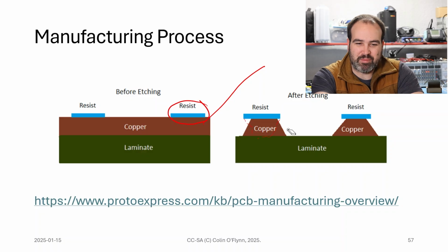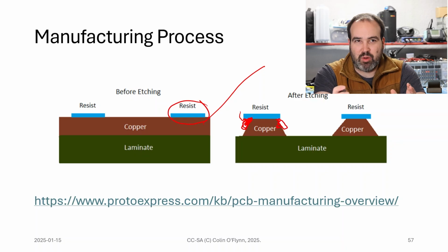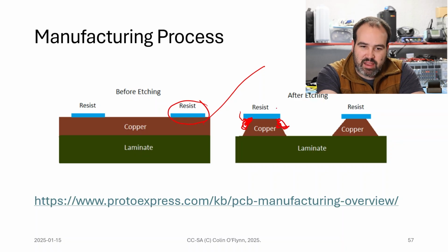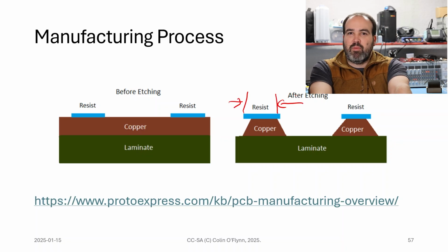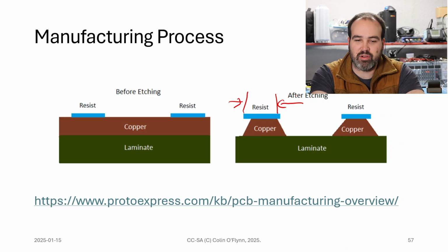You end up with this problem that basically you have this under etch, right? So under the resist, etching happens here, so the trace widths get too narrow. And so whatever our design traces are, they can be a tiny bit narrower than we meant them to be. So obviously, if this width, this goes back to our trace space, is really small, it's easier for these to under etch further, and so it's more likely we're going to have opens in our traces. So this is why smaller traces get more and more expensive.